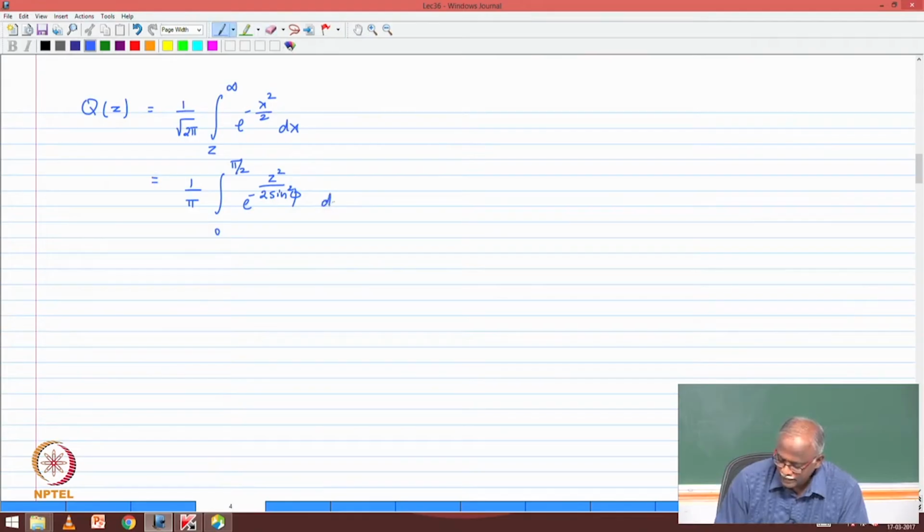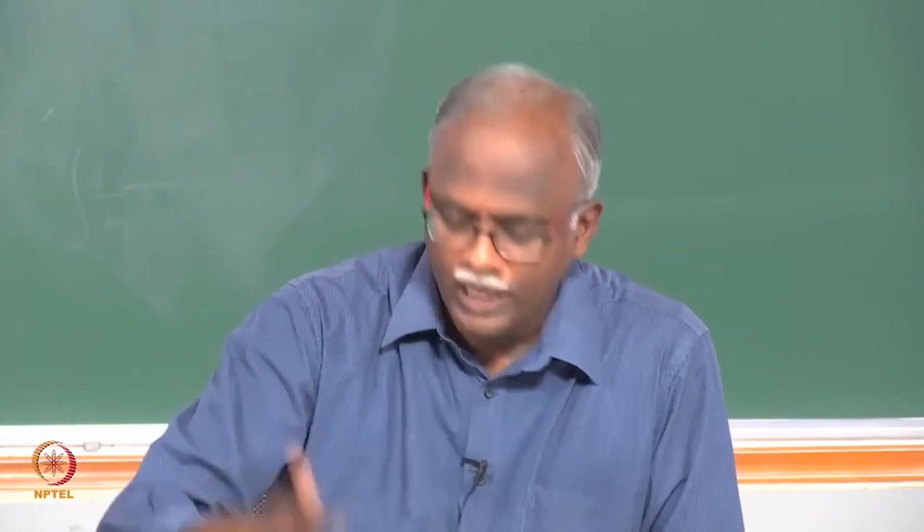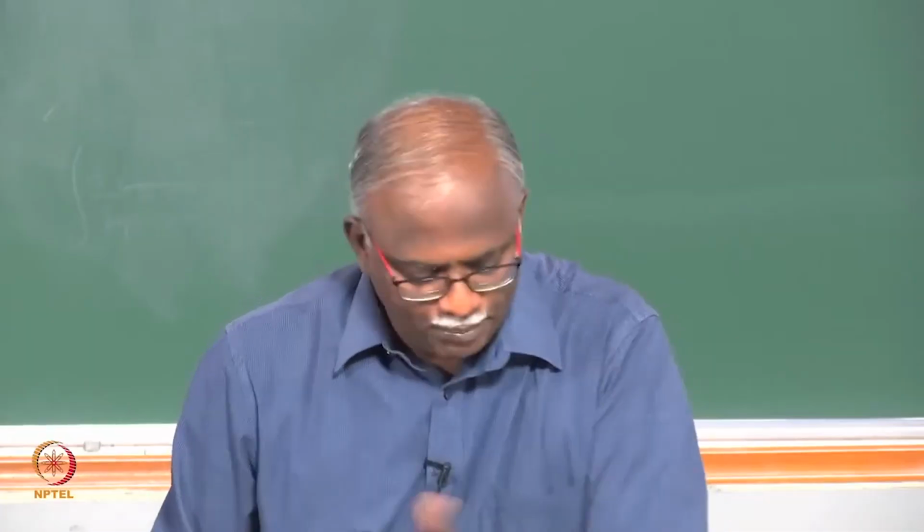Okay. So that would be our equivalent expression that we want to leverage. Now we said that the probability of error of BPSK has a Q function, and likewise there are several modulation schemes. In fact, most of the QAM modulation, 16 QAM, 32 QAM, all of those will have a Q function as part of the expression for error. So any of the general family can be handled in the following fashion. As an illustrative example, we took BPSK.